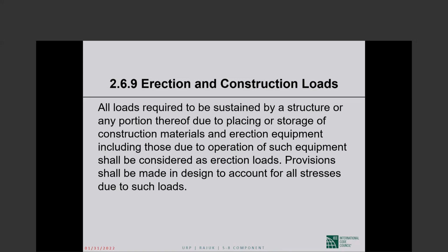Now, it's not just that concrete building. Any building will see the highest loads it will ever see during its service life, during the period of construction. Okay, that's the highest loading, because you store stuff on the floors, workers are walking around, and also the concrete is green.